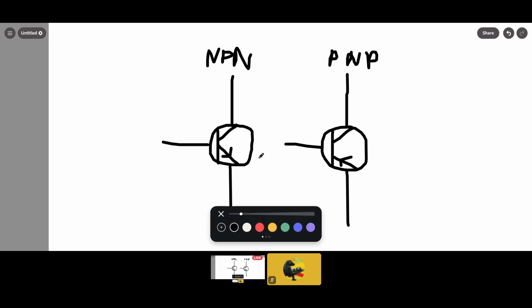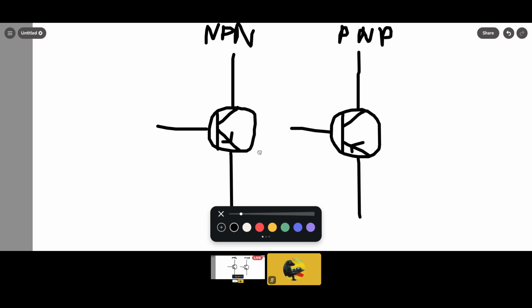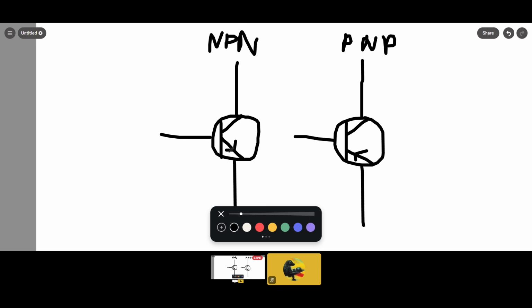How you can tell is that you see in this circle bit here with the lines, this arrow. When the arrow is exiting this vertical bar, it is NPN. And for the PNP, when it enters the bar, then it's PNP. That's how you differentiate it. So it's actually a very minute detail, so you need to be extra careful, and you should spot it.